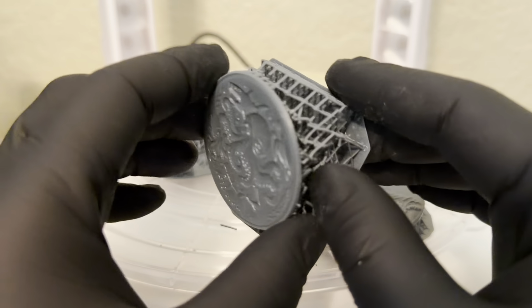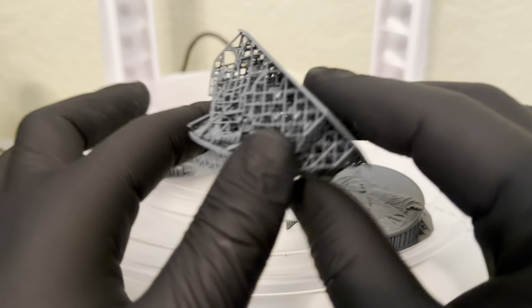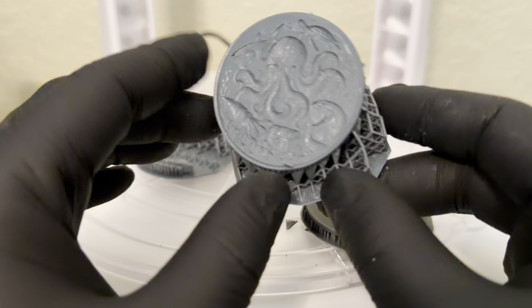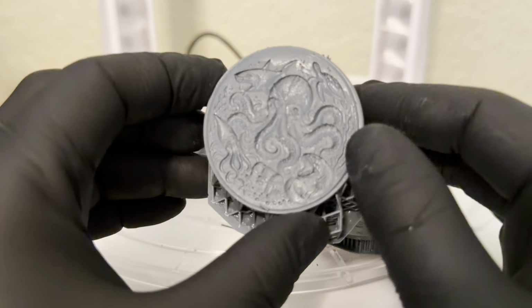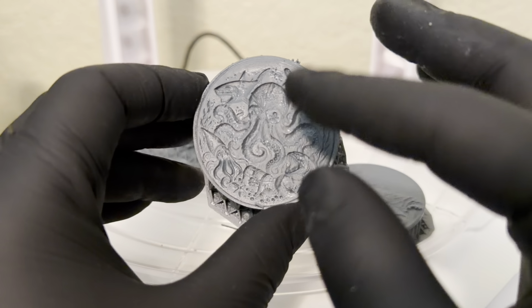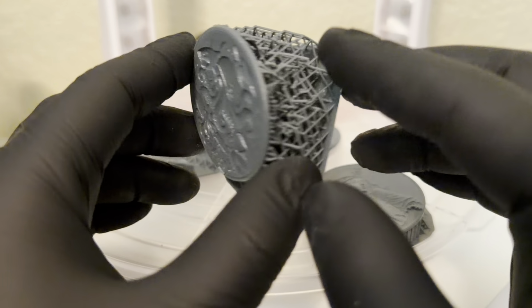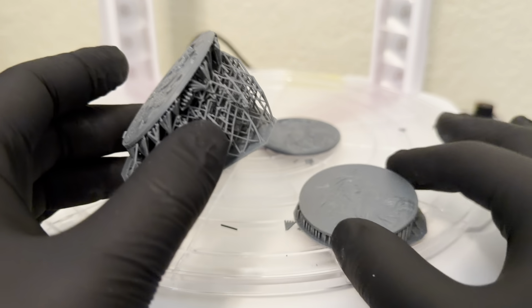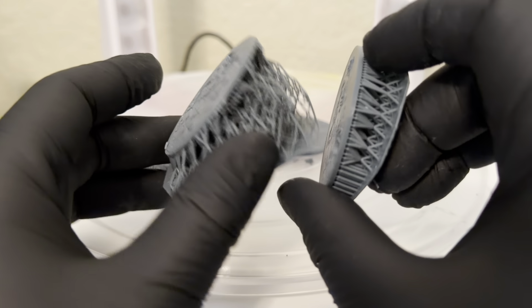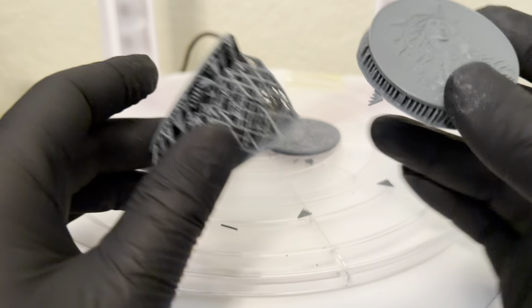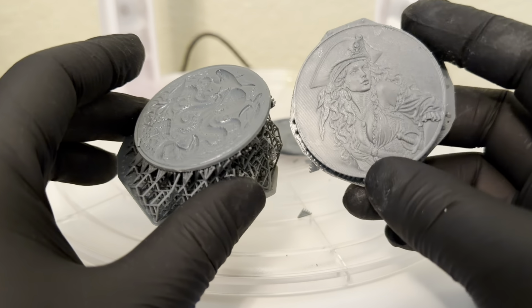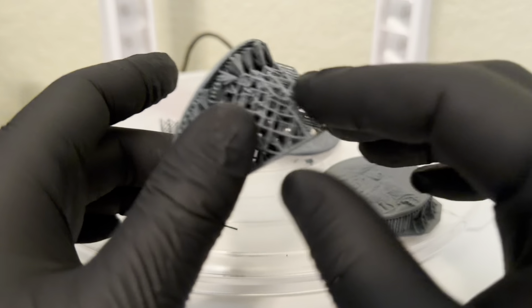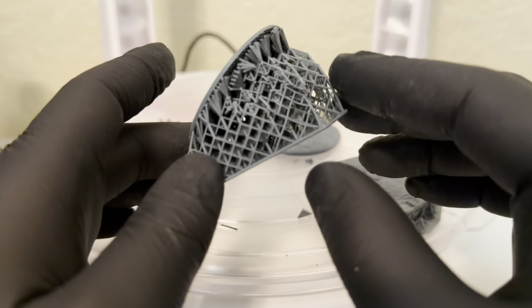Maybe we could use it as a press. We'll hold these to the side for now, but so we're gonna do it like this. This one looks like you don't see the lines. So this is pretty vertical right here. So we're gonna make this one more vertical, but use less support. I mean, because it's pretty light, so I think the automatic support was a little too much support there.